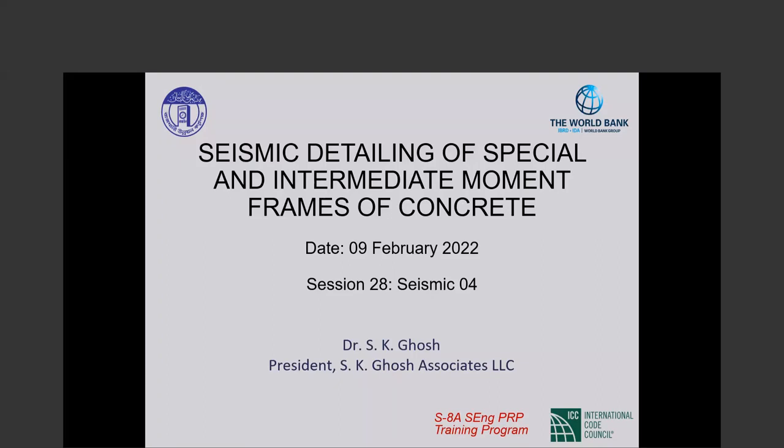No design category A in all of Bangladesh. If you have design category B, your moment frame can be ordinary moment frame. And then you go with the non-seismic detailing that we discussed on an earlier day.